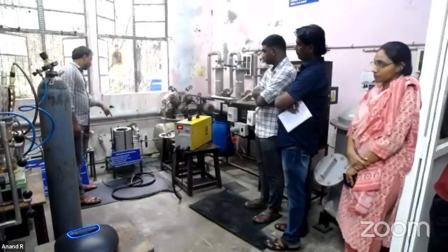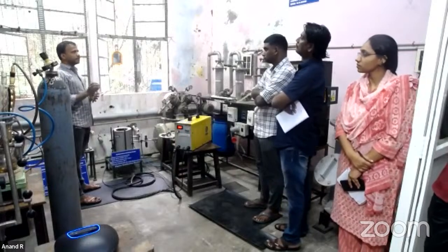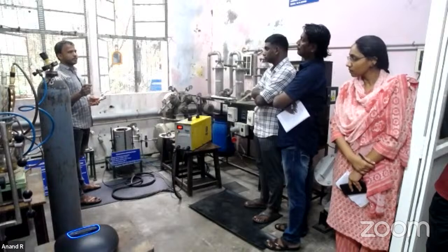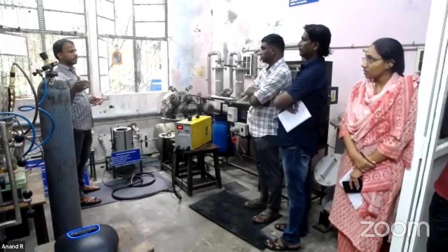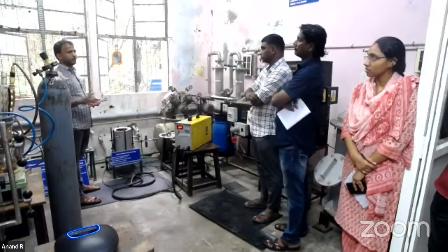Now there will be a gap of more than 5 to 6 mm. So for initiation, you have to maintain a minimum gap. After the arc is initiated, you can increase the gap up to 1 to 1.5 centimeter. It's 10 mm to 15 mm. The arc will be present.